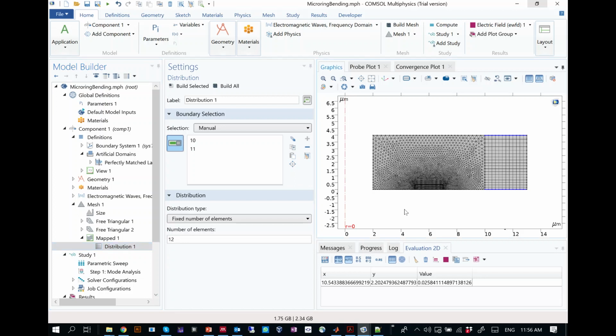But who knows what a perfectly matched layer is? What is it about? We change the equation. We amend our equation just to dump the waves on the boundary. Yeah, exactly. So this kind of absorption layer where you start to increase your absorption, but you increase it smoothly, so that you get no reflection.